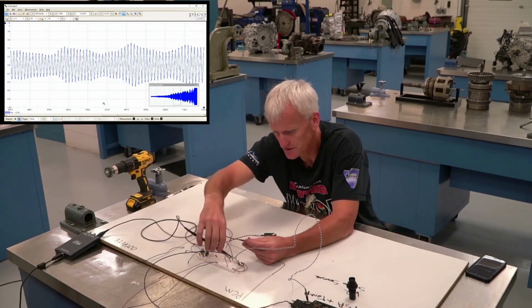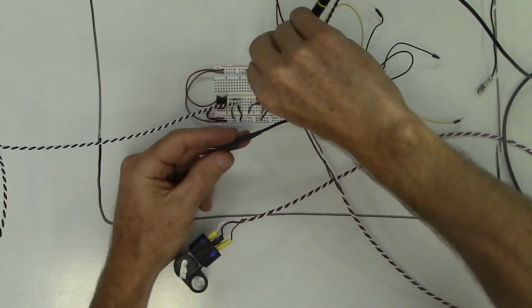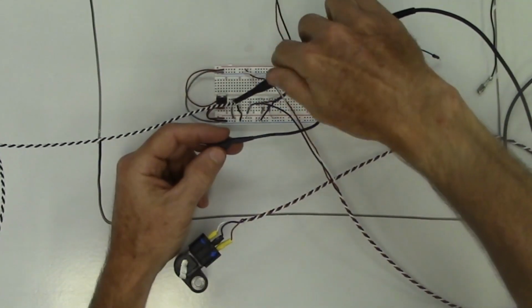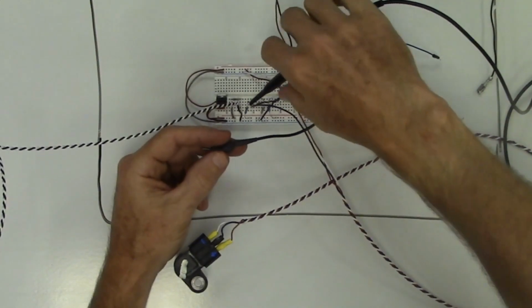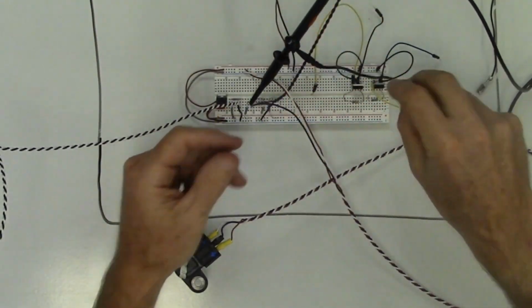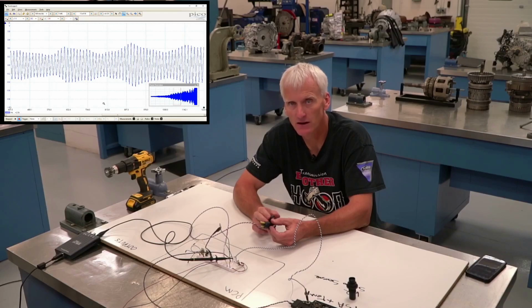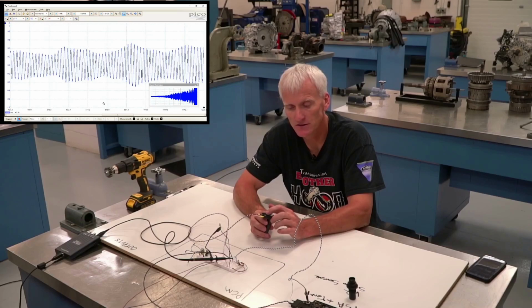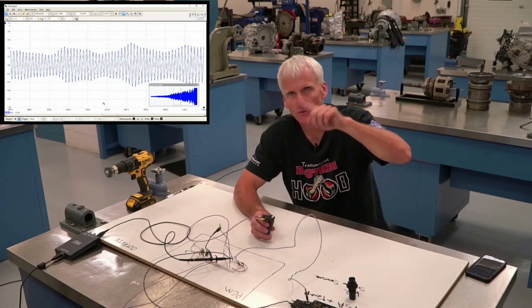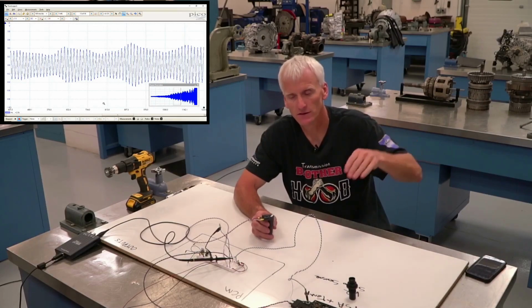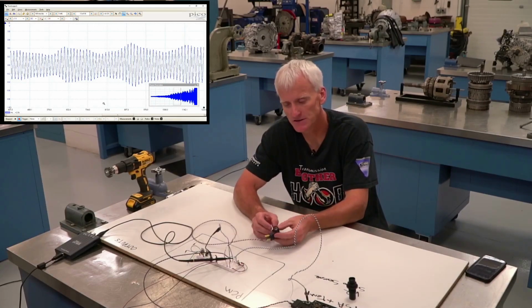And a Hall element works in a similar fashion in the fact that it does use a magnetic field, and as the flux lines change, we're going to get a reaction. But what makes it different, it's still got a magnet in there, but the magnetic flux lines influence a Hall device, a Hall element in there, and it toggles a circuit to ground out this signal wire. So instead of getting a sine wave, you're going to get a square wave, and it's going to be DC, not AC.